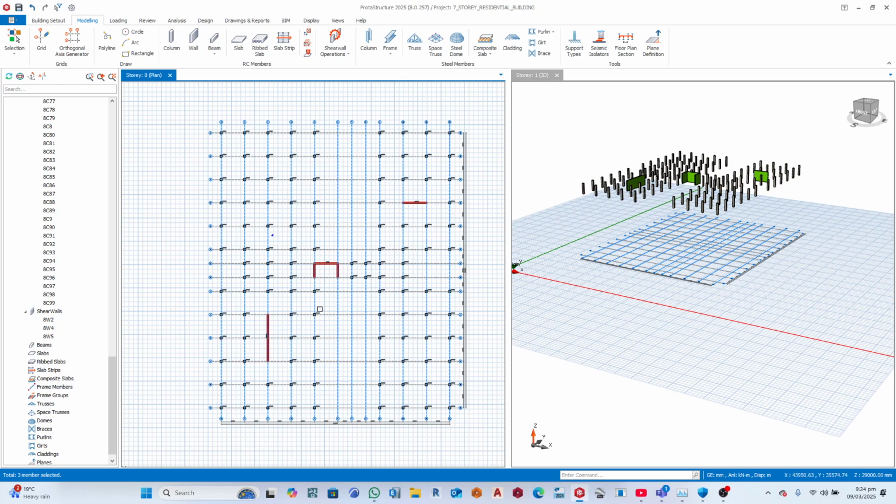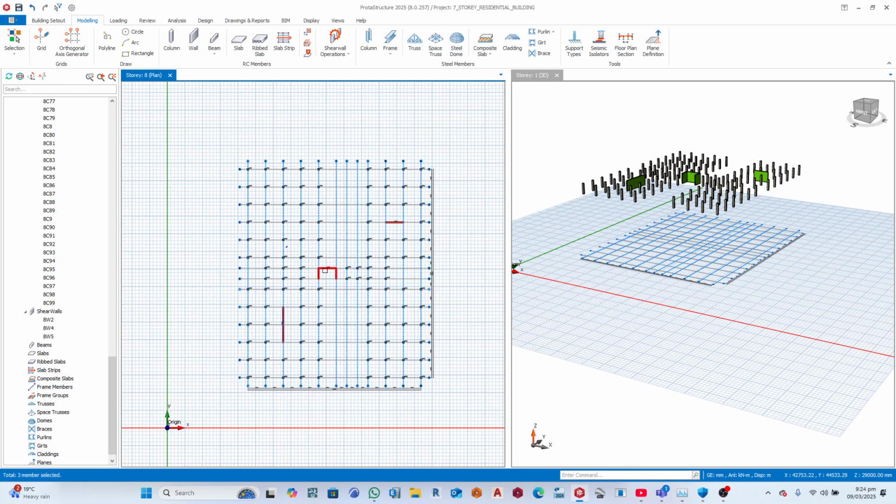If they are braced, they transmit all the lateral loading from the wind, any lateral loading, to these structures, the core and the shear walls. Then all they deal with is axial load. They'll just carry the load and transmit it down to the foundation. They won't be susceptible to lateral loading, provided there's connectivity among all these structures.